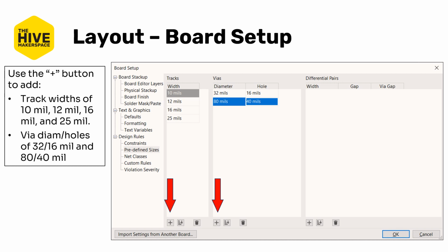The 40 mil hole is about 1 millimeter, and that'll fit a standard pin header if you need a via but don't have access to electroplating, like for instance at the Hive. It's also good for a lot more current. Now, it's not typically necessary since you can use multiple small vias instead of one large via if you needed to pass a lot of current and didn't have a large via. Smaller vias can also be nice because they're so short, they can pass large amounts of current briefly without too much temperature rise, but it's a discussion for a completely other day.